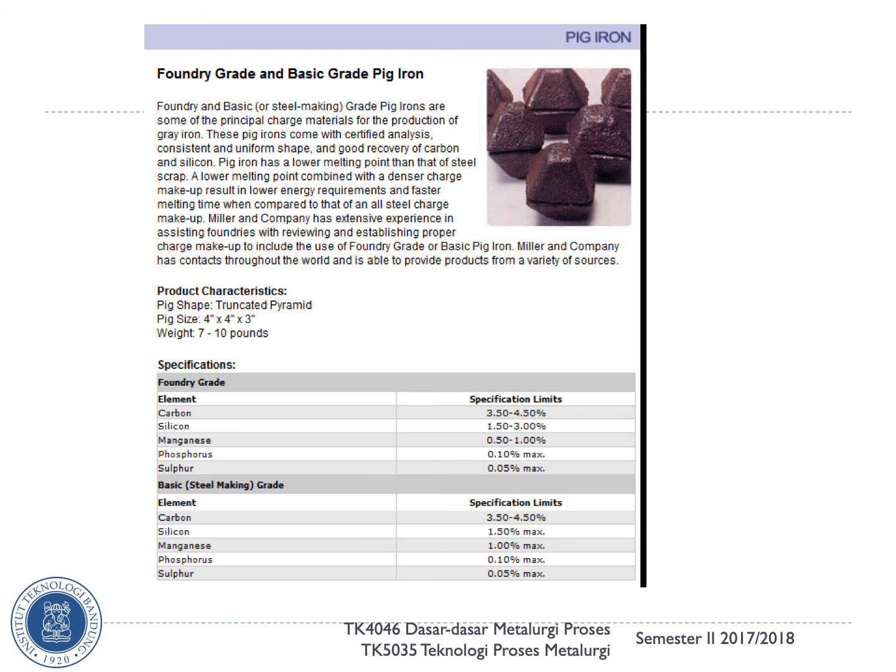because it is still quite crude iron, it will have some elements that are still in the iron, for example carbon 3 to 4%, silicon 1.2 to 3%, 1.5 to 3% manganese, phosphorus, and sulfur. While the other one is pig iron for steel making grade, to make steel, for example carbon, silicon, manganese, phosphorus, and sulfur.